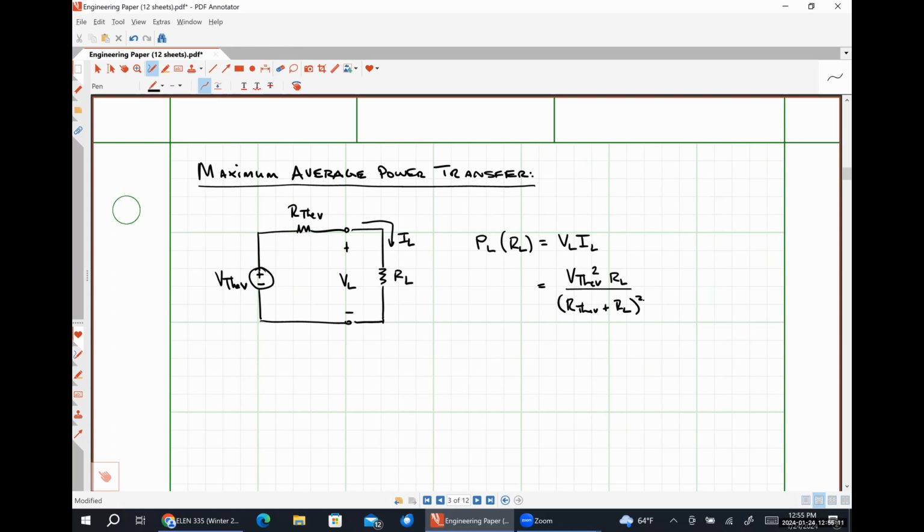And it obviously depends on what the value of the Thevenin voltage is, the value of the load resistance is, and the value of the Thevenin resistance, right? The maximum power that could ever be absorbed by our load resistor occurred when RL was equal to R Thevenin. And we wound up getting, sorry, this should be 1/4, not 1/2, my apologies, V Thevenin squared divided by R Thevenin. Any of this sound vaguely familiar?